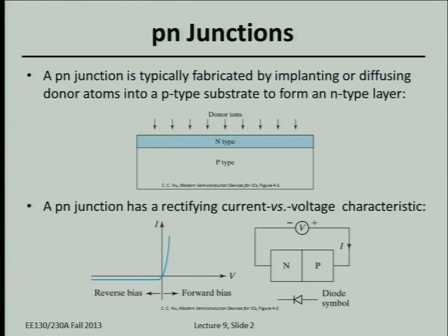like embedding these dopant ions into the surface of the silicon wafer. And then you have to heat up the wafer to like 1,000 degrees Celsius to heal the damage caused by that shot of the donor ions in this case. So you get the crystal to heal itself and to have the implanted donor ions reside on substitutional lattice sites so they can form covalent bonds with 4 nearest silicon neighbors. And then they can donate their electron to the lattice.